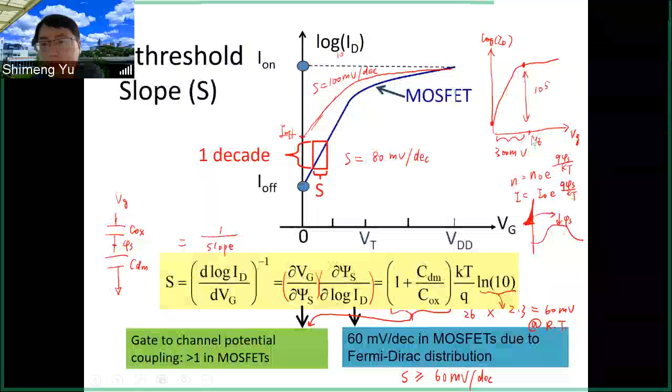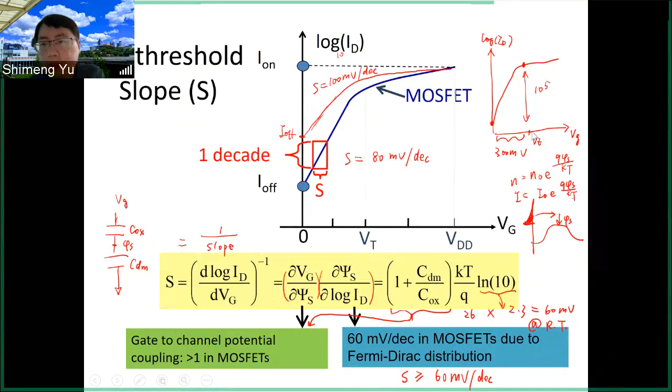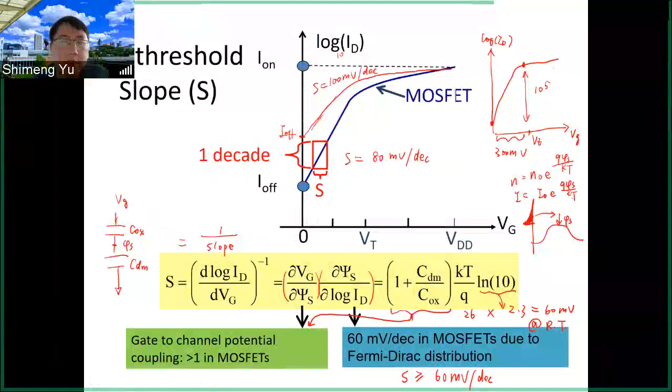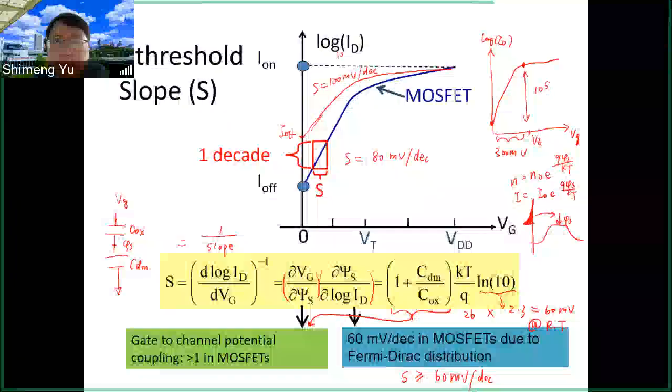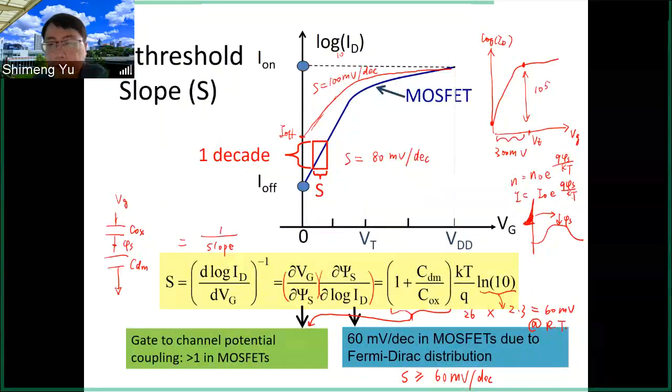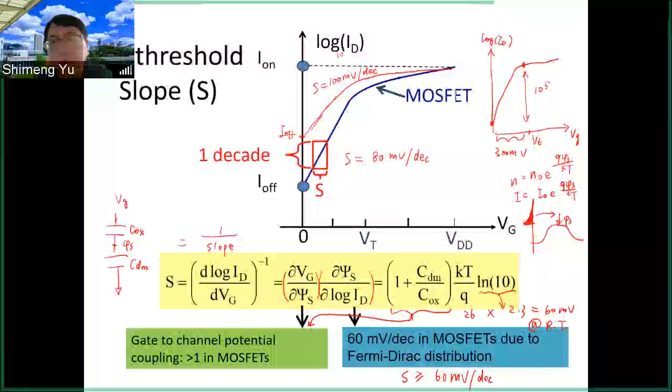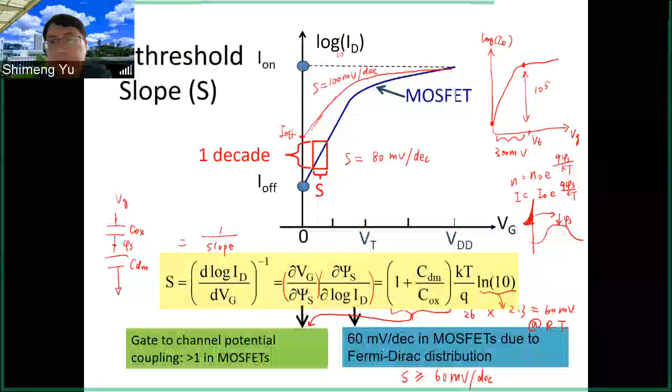That means this is for the threshold voltage. That means your gate voltage, the VDD, the power supply, needs to be above that. So for today's power supply, typically if you look at TSMC 7nm process, the power supply is like 0.6 or 0.7 volts. This is larger than this 300 or 400 millivolts because you have to make sure you turn on the transistor. So the minimal VDD today is like 0.6 volts.